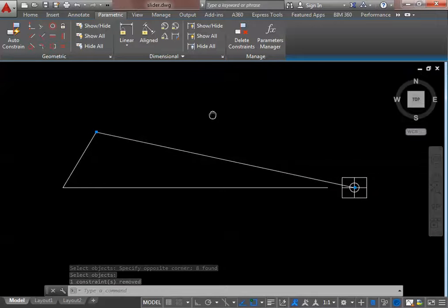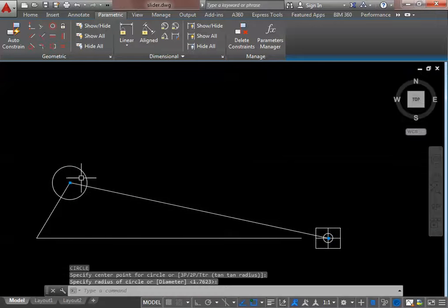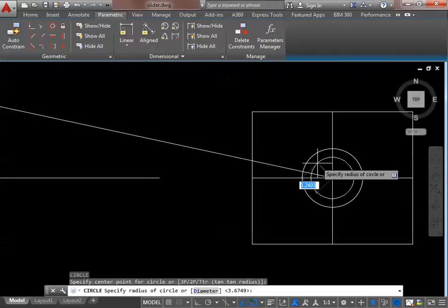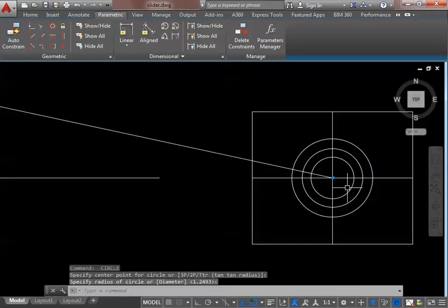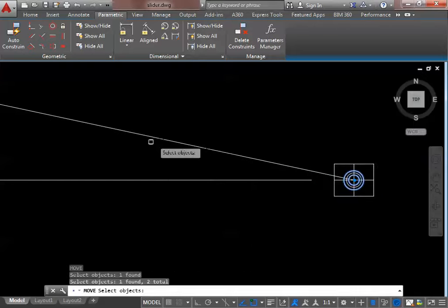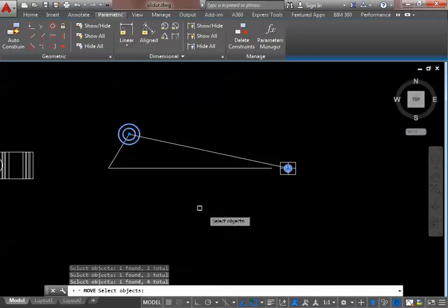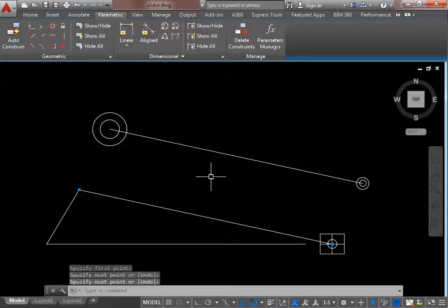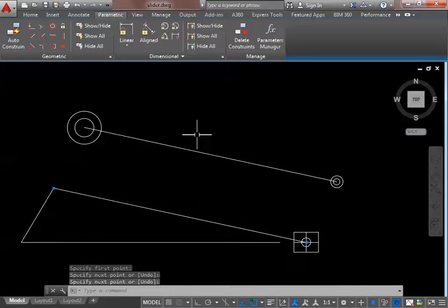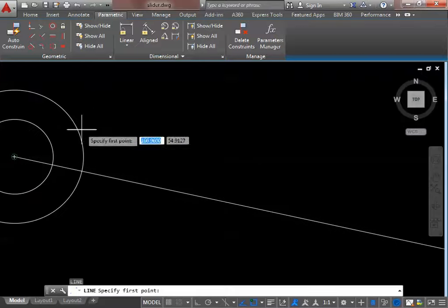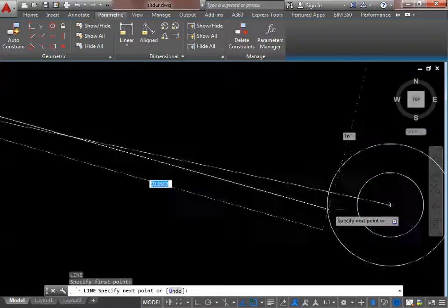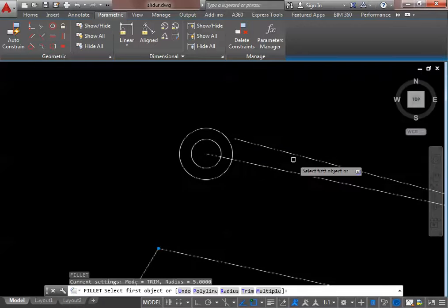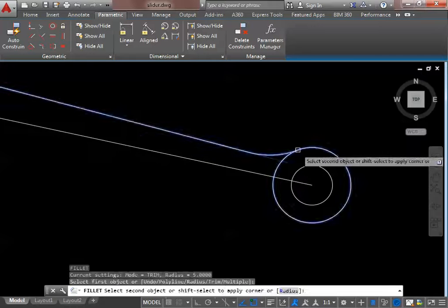Now here I want to draw a connecting rod, so first I will have to make the connecting rod of exact size. Let us have big end here and small end to be here. Now move those parts. We'll draw axis to axis thing, and randomly let us have this dimension, and we'll be having a fillet with this and this.